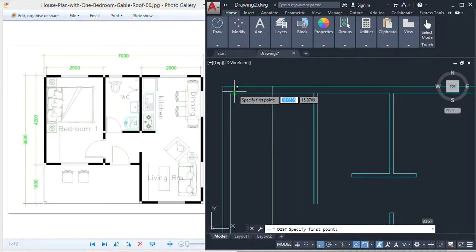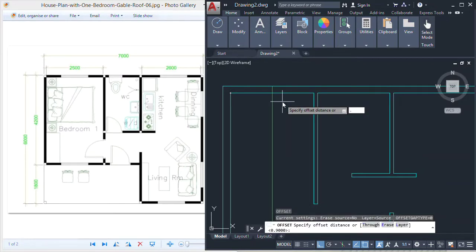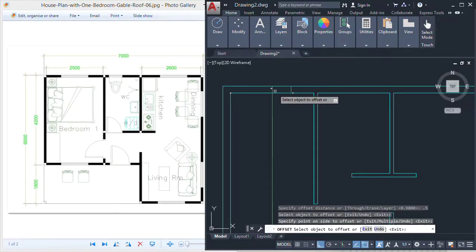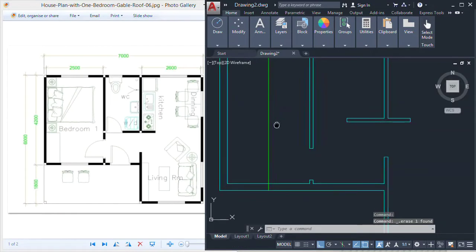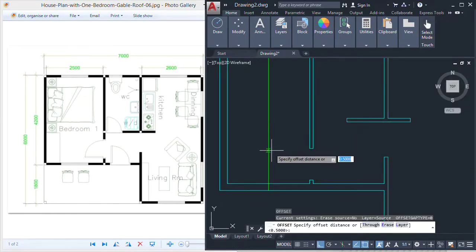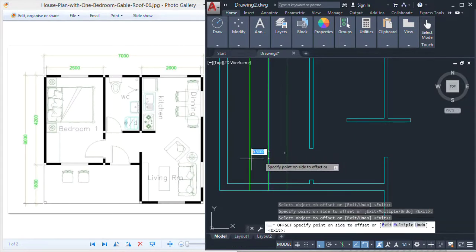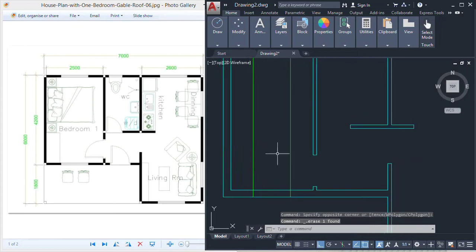I'm gonna see the distance here is about 2 meters. I'm gonna give 50 centimeters to each part, so it's a close window, but I think it works for this house. And I'm gonna ortho another 50 centimeters this line and this line, and then completely delete this.